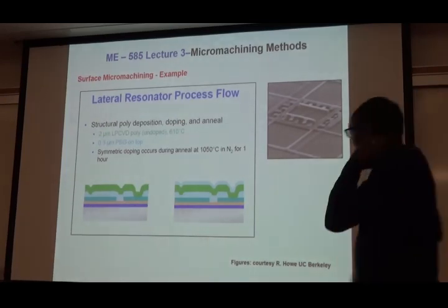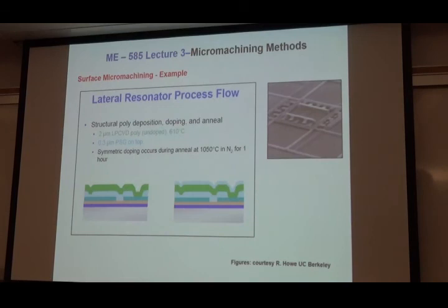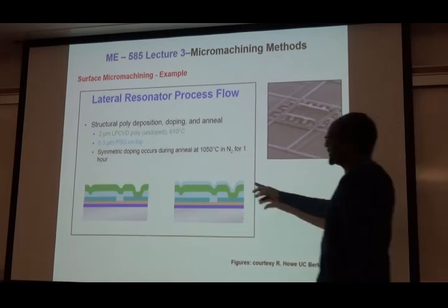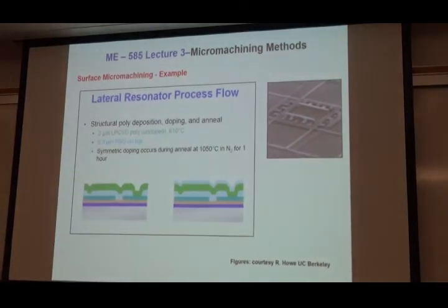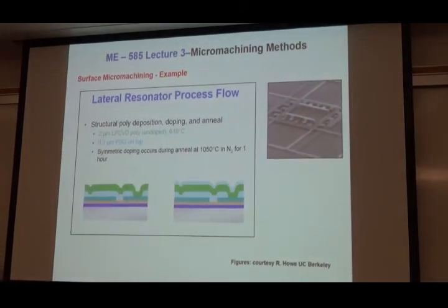Now, I got this guy, 2 micron deep, something that you haven't seen so far. Typically we've been playing with 0.15 micron, 0.2 micron. Then I have this 2 micron guy and I want to pattern it. If I use a photoresist, remember everything etches, it's just a rate. Now if I use a photoresist and I keep it for about half an hour, before I reach the 2 micron, the photoresist will be stripped out. It will be etched that way. So I have to use another kind of material to mask things.